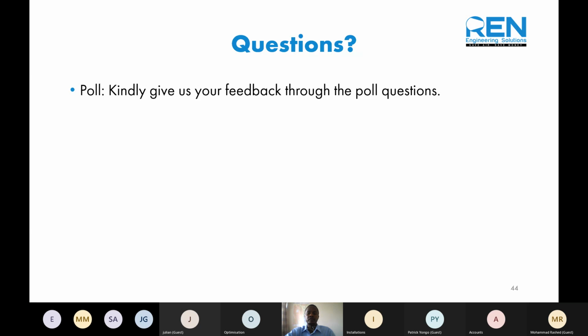Okay, so we also have a question from Patrick, who is asking, do we do air sampling after the air filters or direct from the user point? As you do your risk assessment, it's important to determine what are the critical control points. You can decide to test after the air filter, for example in the compressor room, to determine if that filter is doing its job of reducing the risks posed by particles or oil.